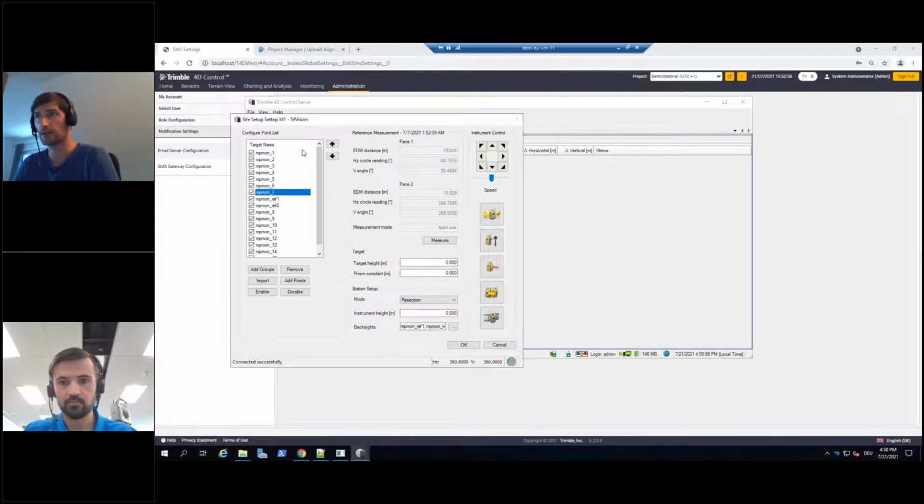If you look, I scroll down. So it's from the same round measurement in this example, but you can basically update a reference measurement for a certain target at any time, right? And then the date and time will differ up there. This is really helpful information because it helps to assess displacements, in particular if the reference date differs from target to target, as I said.